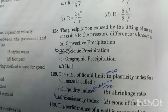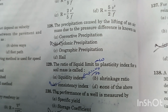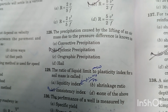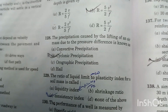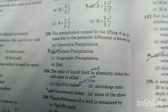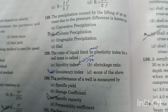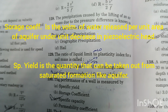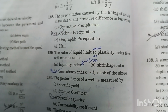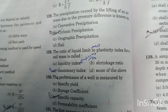Option C is the right answer. And the ratio of natural water content minus plastic limit of the sample to the plasticity index is known as liquidity index. Question number 130. The performance of a well is measured by specific capacity. Option C is the right answer. Specific capacity is the ratio of discharge per unit drawdown of a well. It measures the efficiency of the well. So option C is the right answer.